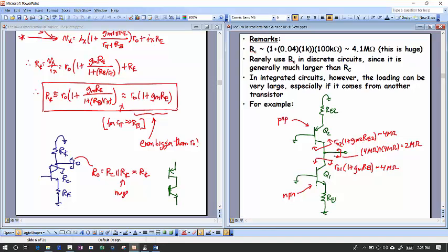So for example, say I had this, okay, which is a typical type of transistor configuration you're going to see. And so I'm already talking about things that I haven't taught you yet, but already you should be able to analyze this just with what I've told you. Because if you look at this, I'm taking this transistor Q1, so think of this as where the input signal is coming in. And I'm loading that instead of with an RC resistor, with another transistor. Except this one's a PNP device, so that means my collector is below the emitter when I'm drawing this thing. And they're both sort of exactly the same. I got an RE1 and an RE2 on that.